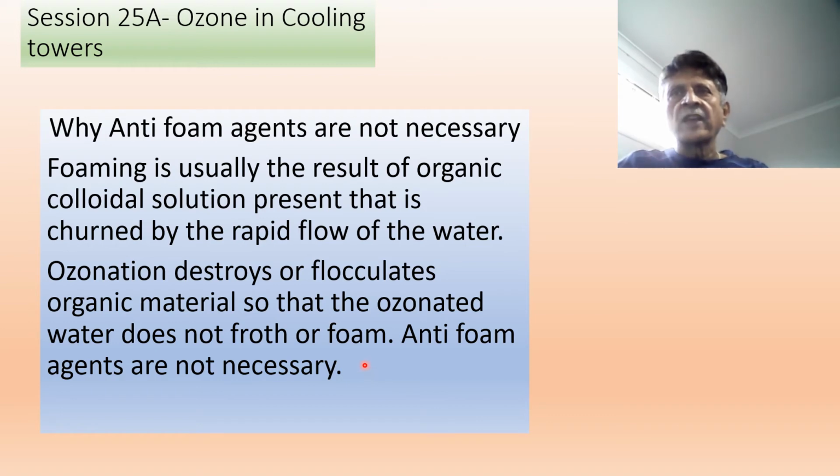Remember, frothing and foaming is an enemy for energy transfer or heat transfer because it will reduce the contact time and contact surface of the water in the chiller tubes, and therefore less heat is transferred from the hot chiller's refrigerant liquid to the cooling system, cooling tower water.